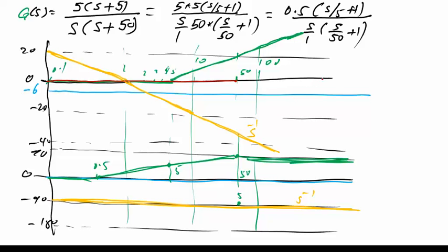So then we take the 500. Yeah, this is the 500. This is approximately the 500 frequency ratio, and it goes minus 20 dB. So it goes through this point. This is minus 20 dB, the slope, right? So it goes 0 to 50, and then, yeah, good, very good. What about the phase?